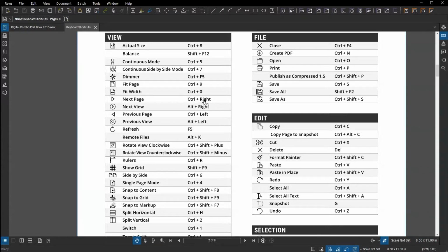All these keyboard shortcuts that are here, just the default values of those, these are customizable. So if you want to use T for something besides text box, you can remap that to be a different function. On your Review menu, about halfway down, there's the keyboard shortcuts option here. You can then go into that and find the tool you want to modify and change, and then remap that to a different keyboard shortcut.